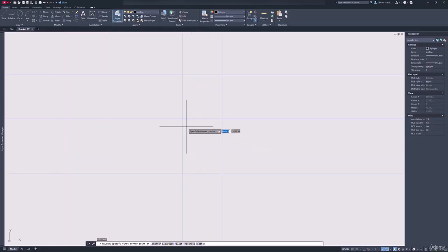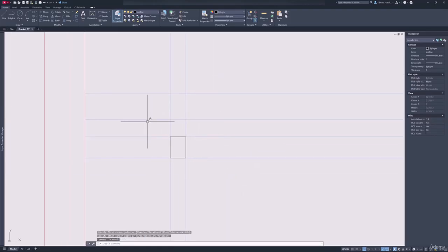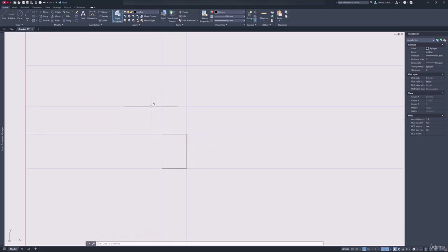And now we'll go ahead and select this top corner here and drag this down to this point. And you can see it's telling us that's 90 millimeters by 125. So I'll go ahead and left click to confirm that. And there we go. It's that easy. We've drawn our first sort of shape. And you can see there straight away our construction lines helping us.